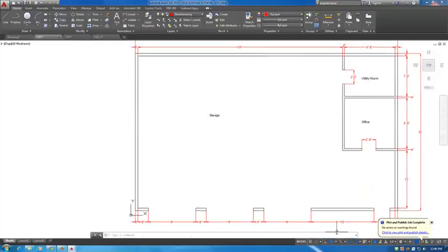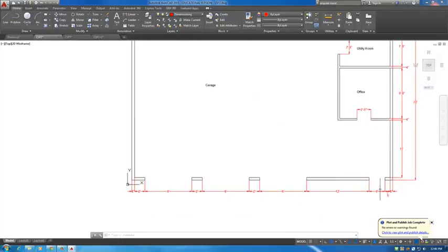When we're talking about doors, doors come in all sorts of shapes and sizes. I put some standard 32-inch interior doors in here. 2 feet 8 inches is 32 inches. For an exterior door, I have a 3-foot door. You also have to think about where the door goes when it opens. We can't put this door right in the corner because it would slam against this wall. Things like that are basic architectural design.